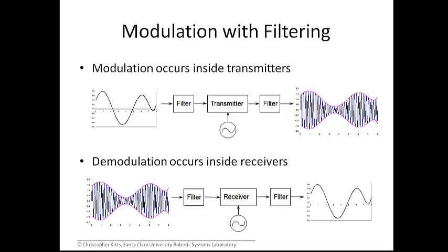And then I get the modulated version at my receiver, and I might filter it for unwanted noise because I'm probably receiving what I want to hear, plus I may be receiving lots of other stuff at different frequencies. So I get rid of that other stuff. Then I go through a demodulation process in the receiver where I'm combining the modulated wave that I've received with the carrier wave to get the demodulated wave. When I do that, I generate two frequencies. I'm going to filter one of those out, the higher one. I'm left over with a scaled version of my original wave.